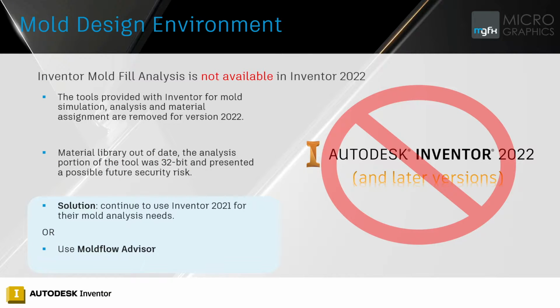Now, the Inventor mold fill analysis is not available in 2022 onwards, right? So this has been removed, so I've just put in a note just to make everyone aware. You might be working on Inventor 2023 and try and follow along on some tutorials on the internet, but the tools provided with Inventor for mold simulation, analysis and material assignment are removed for 2022.